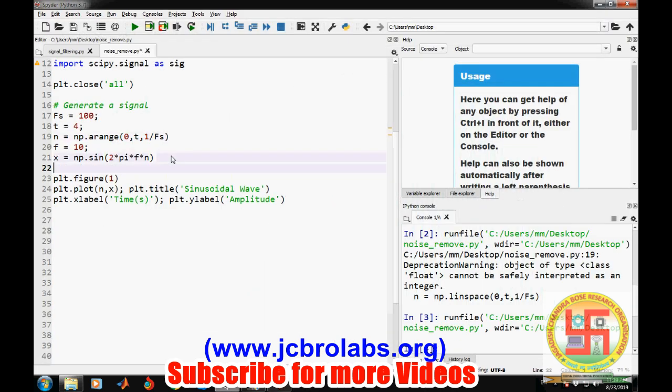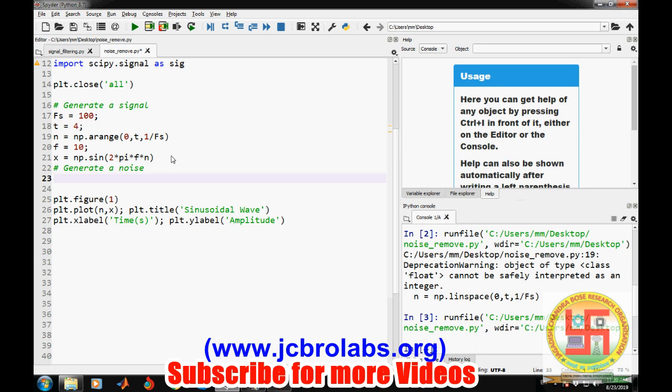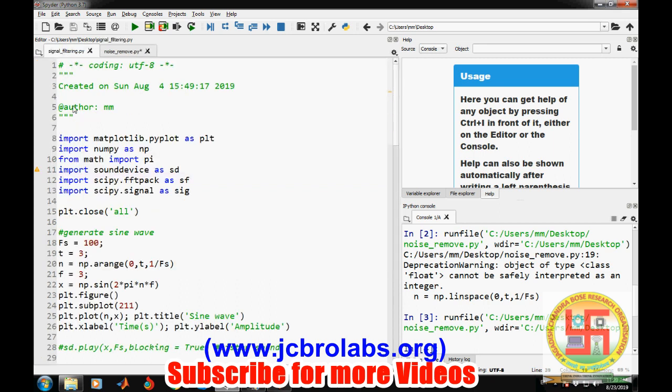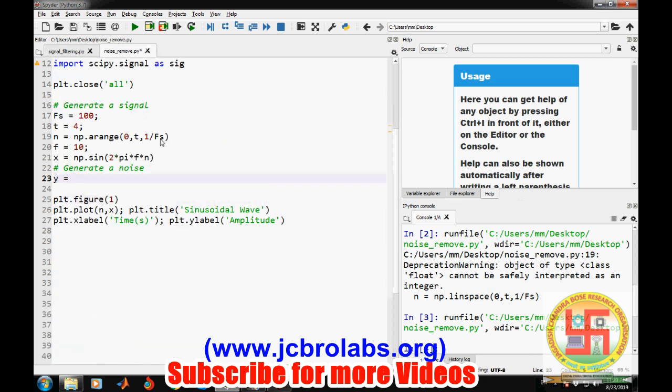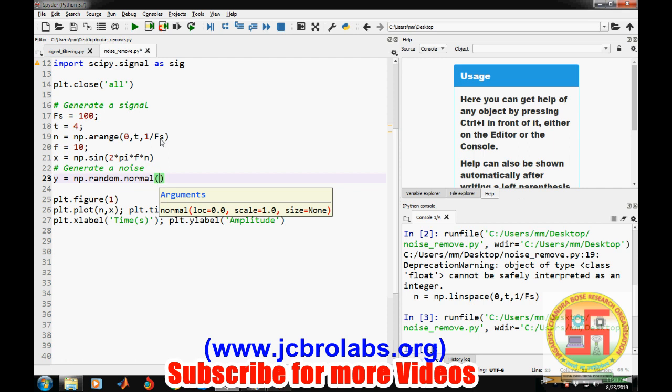Okay, now we'll generate a noise. Signal is generated, so let's generate a noise. So let's say y equals, there is a function np.random.normal. It needs three arguments. First is the mean, so let's say we are generating 0 mean, then the variance, let's say 0.2, and the length of the signal, or the number of samples which we want to generate. So we can have np.size of x, because it has to be a similar length. Okay, now let's generate it.